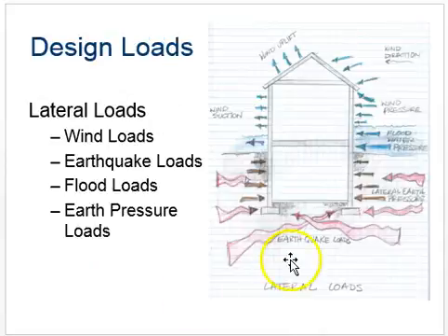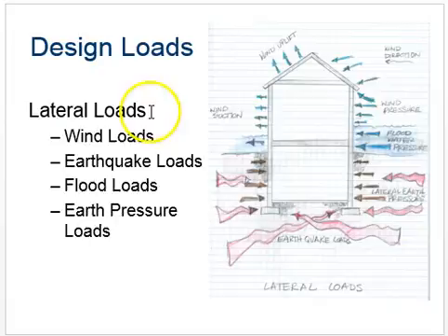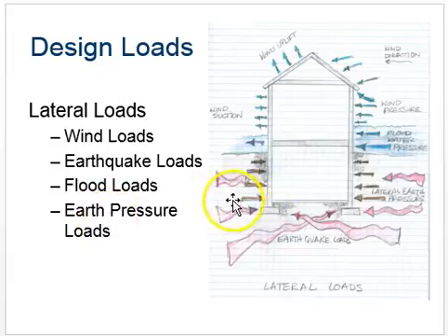Design loads also include all of these lateral loads. When we say lateral, we mean sideways loads. Wind, earthquake, floods, earth pressure down here pushing on the sides of our footing.